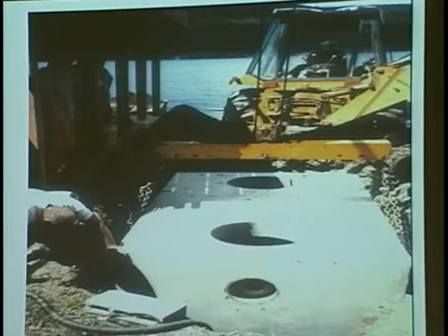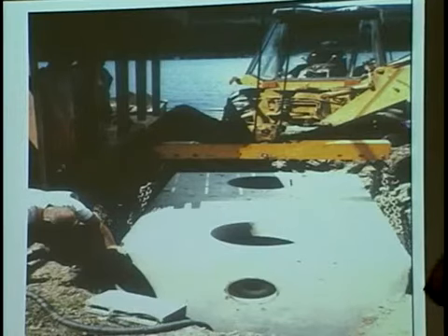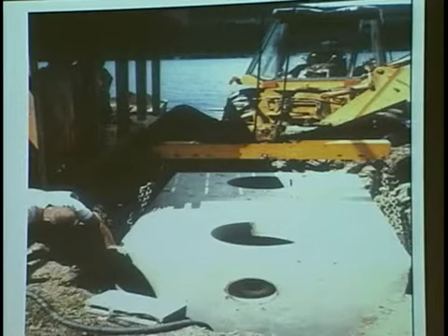But if you've got an existing structure, somebody mentioned it here earlier, the older homes, what do they have? I think you mentioned it, Bob. What do they got out there? Nothing but a 500-gallon steel tank and maybe a 55-gallon barrel for leaching. This far from the lake, in coarse fractured shale. I don't know what you have here on the shoreline of Chautauqua Lake. Ours is coarse fractured shale. You try to do a perk test in it, you can't pre-soak the hole because it goes right out through that coarse fractured shale. Are you getting any treatment in that coarse stuff? No. It's going right to the lake.